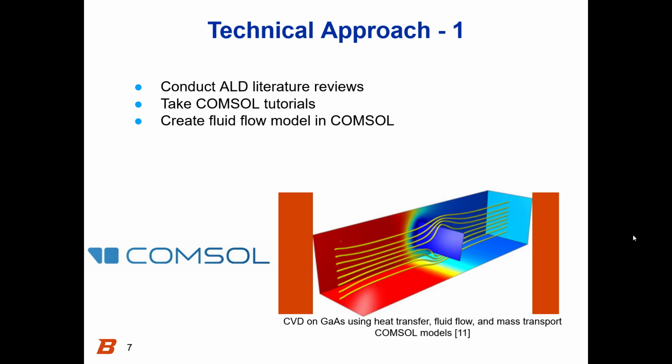So our technical approach is we started with in-depth literature reviews and COMSOL tutorials. Then we created a computational model using the transport of diluted species and laminar flow modules to show the behavior of trimethylaluminum and ozone deposition on a silicon substrate in an ALD chamber.